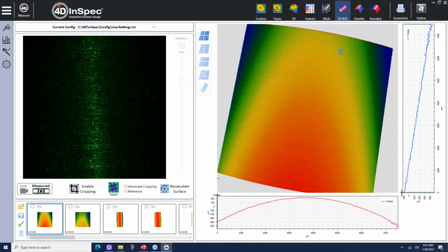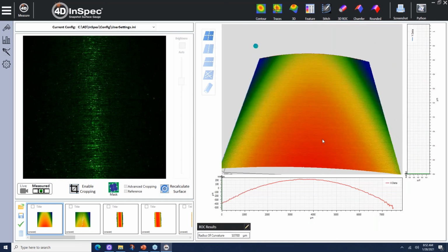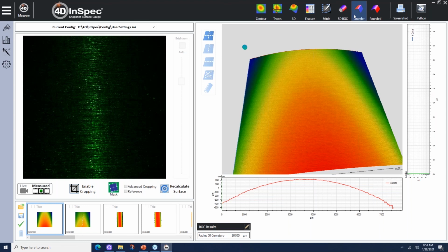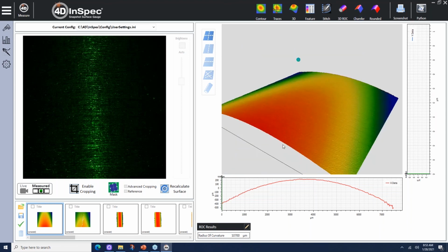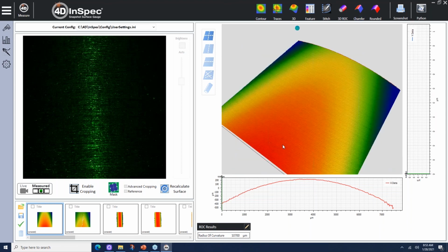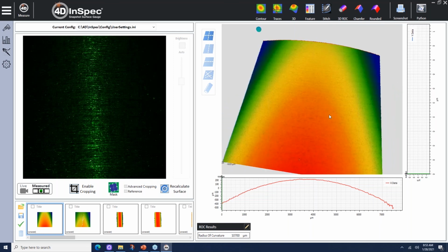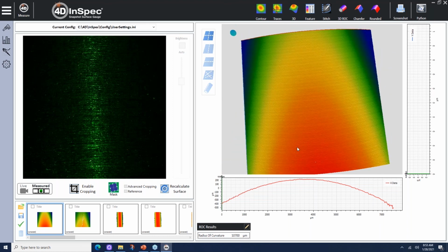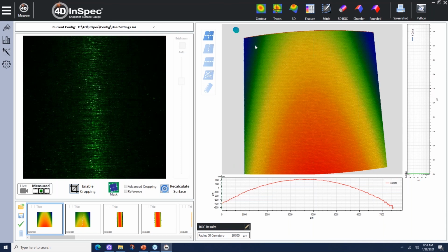So I'll put this into the 3D radius of curvature. Put my cylinder into this edge break analysis, which is the 3D ROC, and then get my radius curvature result right here. So just like these two, it's removing any tilt I had with the inspect, because I wasn't perfectly orthogonal to this microscope stand cylinder. But it doesn't matter, it can remove that tilt. And I mean, you can see I was off.